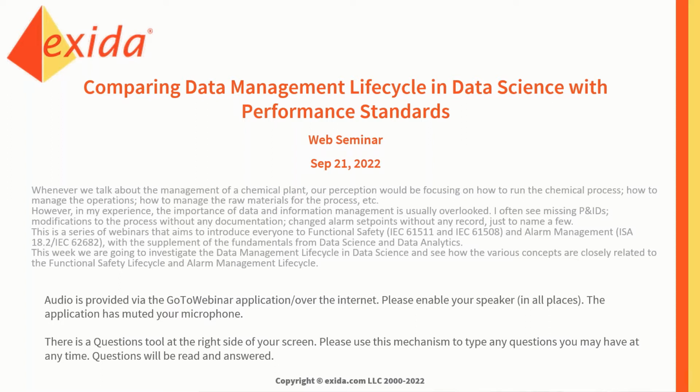However, all these details and data, whenever I go to a plant to do a PHA, HAZOP, some kind of functional safety assessment, or alarm work like alarm rationalization or detailed alarm designs, I don't see a lot of the information, especially about the modifications to the plant. Sometimes the P&IDs aren't up to date, or there's no record about whether there's any change to any kind of alarm attribute. The operators can change whatever they want.